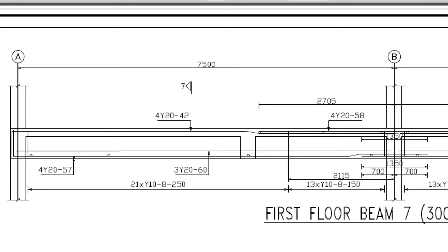Another thing we have to talk about is the links of the bar. The link is that rectangular stirrup. It is also called a stirrup. It is that rectangular bar which all the beam bars will be placed inside. You understand? The dimension of the stirrup will be given in your bar bending schedule as well.